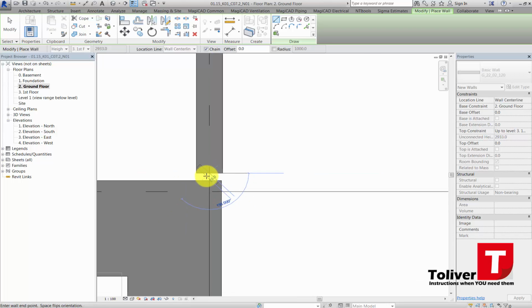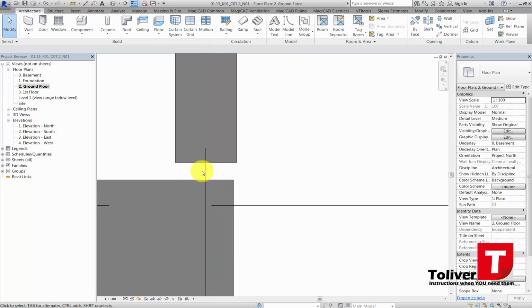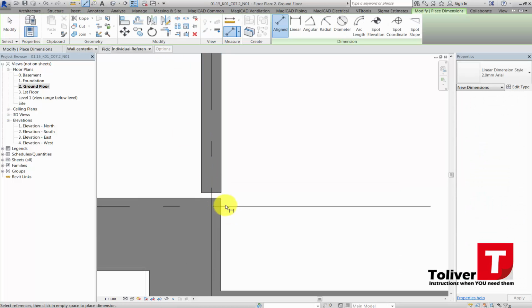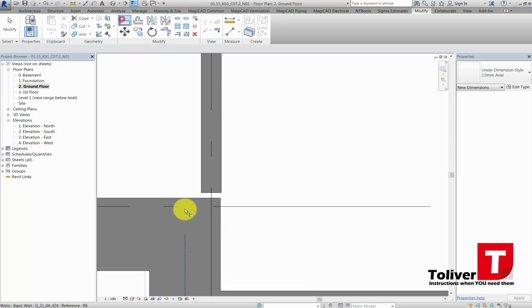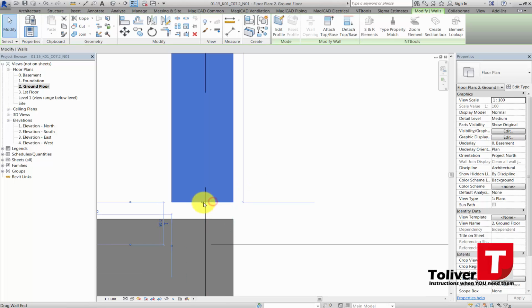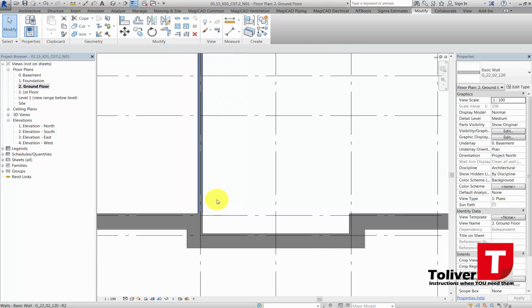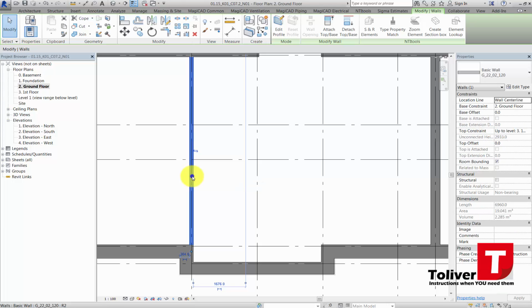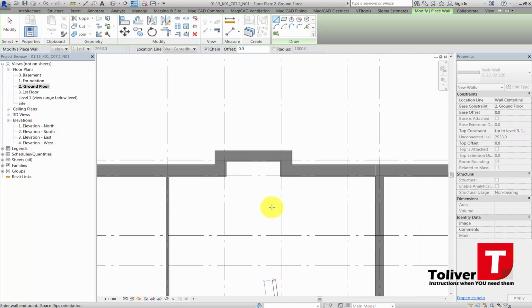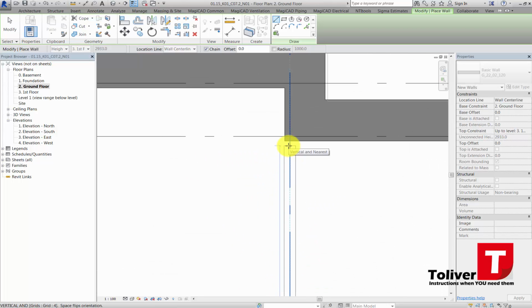The problem is, then I have a problem over here because they don't align correctly. So I can't place it in center. So I'm going to say align this one with that one. Thereby it's moved over a little bit like that, and I just joined them. I'm going to be doing the same on the opposite side, so I'm going to choose it, say create similar, place it up here to this end, and don't connect it all the way.